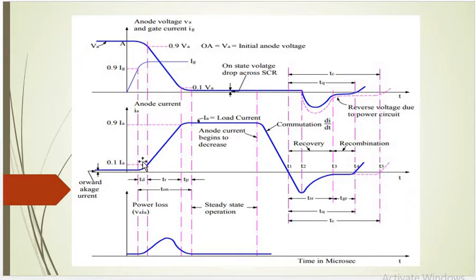Normally in short circuit condition, the voltage across it will be 0 and the current will be the applied current. At the same time, if your circuit is in open condition, the current value will be 0 and your voltage value will be what we have applied as the input voltage. The same we have to consider here. Your SCR is going to act as a switch here. So if it acts as a switch, if you take the voltage across your switch, the voltage value is going to reduce and your current value is going to increase. That we can see here.